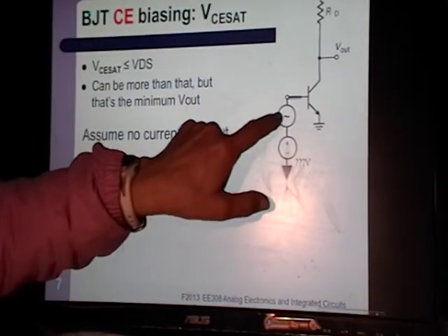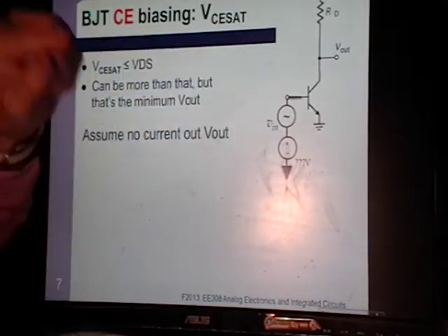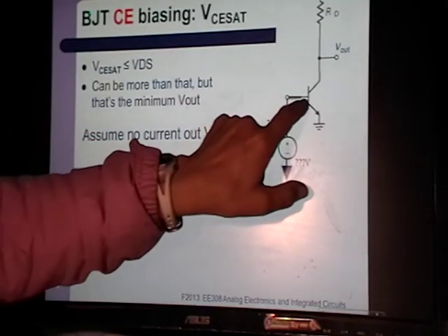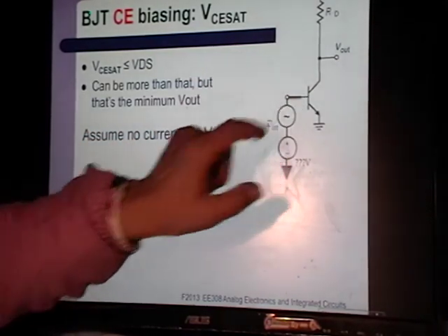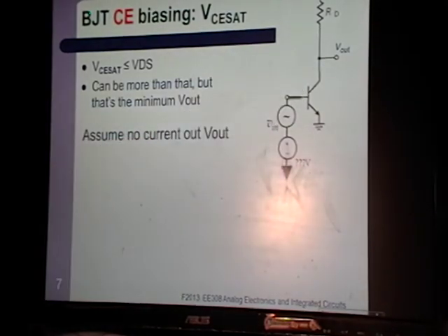So you have a V in across the capacitor. That moving signal part, that's what this is right there. And the voltage that the base sees is the sum of the two: your biasing voltage plus that voltage that's put on top of it through the AC coupling cap.